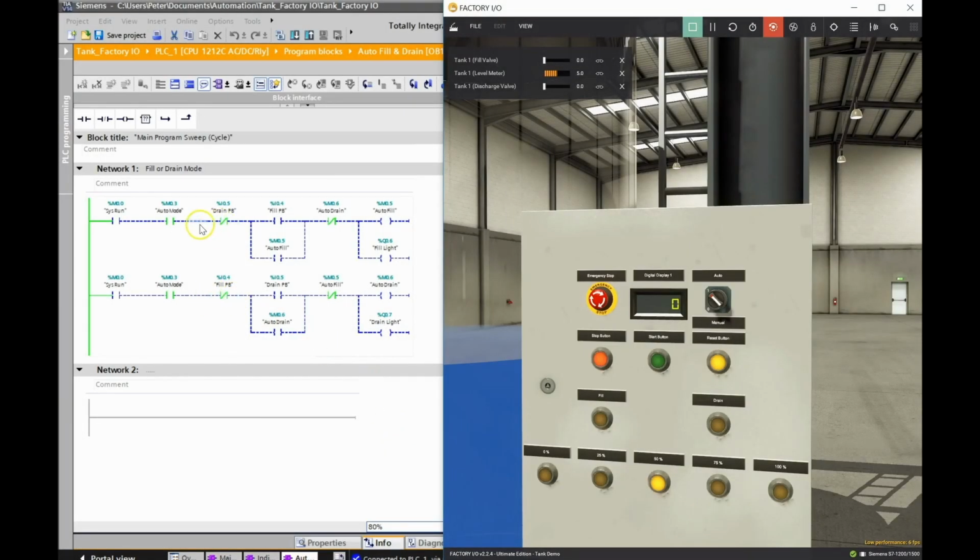Okay, so I've downloaded that. I'm now in my monitoring mode now. So in order to stop this light from flashing, as soon as I start up my animation, I have to reset that portion of the program. I need to hit this start button. That start button will turn on my system run. So let's put this into manual, just so this isn't true yet. So this is not true yet, so we need these guys to be true. So I'm going to hit the start push button, put myself into system run.